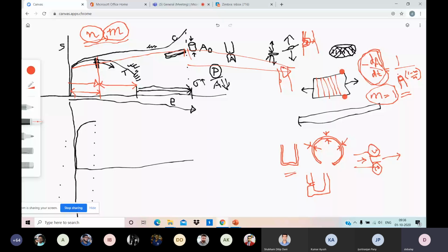So basically, the stable crack propagation happens during this post-uniform elongation stage. So the longer that stage, it means the material has a defect, but with that, it can sustain for a long duration. It doesn't fail catastrophically.